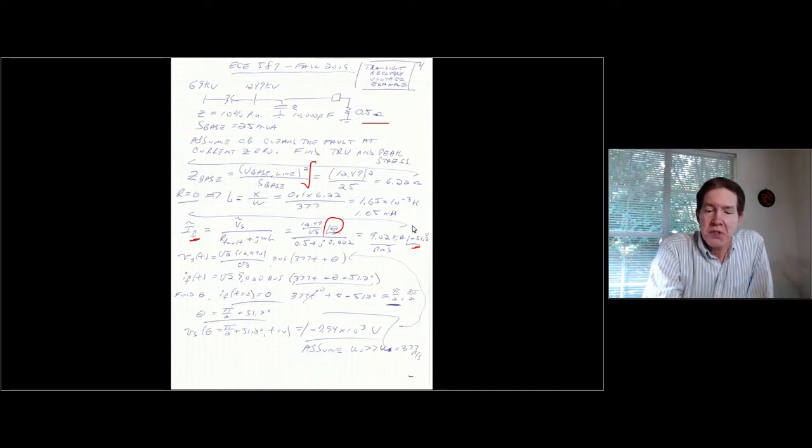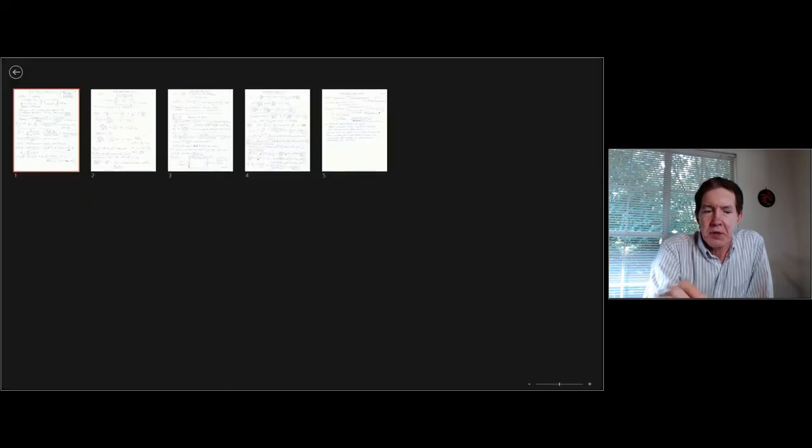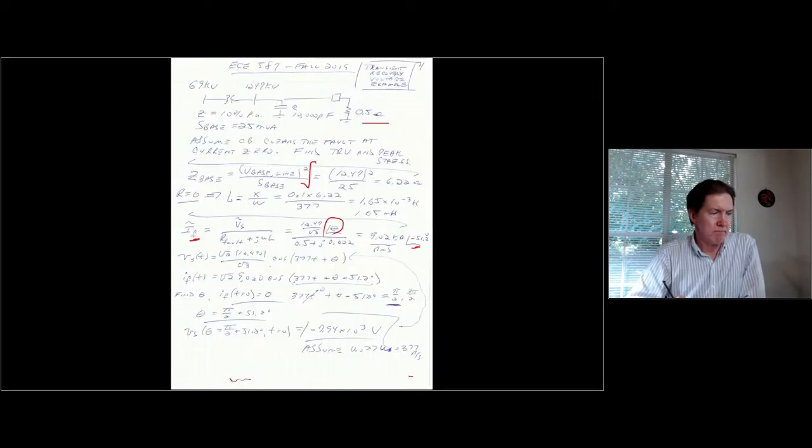Now the form of the source voltage is going to be the line value divided by the square root of 3 to get that to line to neutral, times the square root of 2 to get that to a 0 to peak value. If I multiply that by cosine of 377t plus theta, I have a general expression for the source voltage that I could use. What I need to figure out in this case is what theta is going to be for time equals 0.